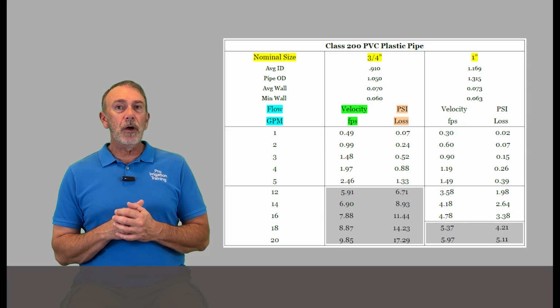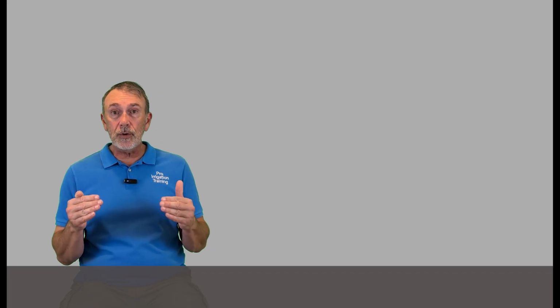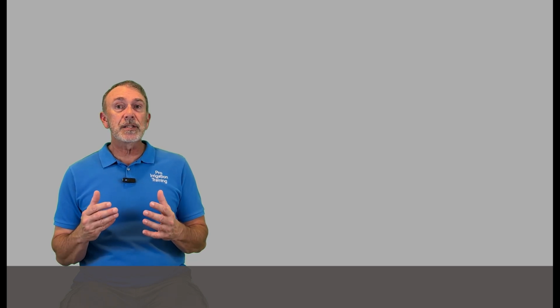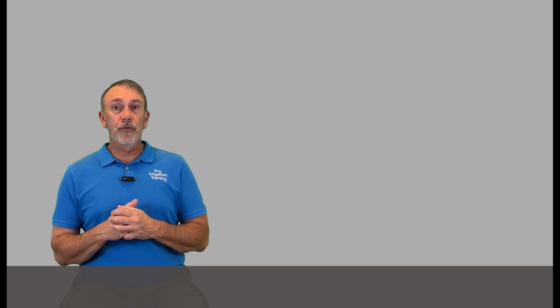And what happens, because velocity is related to friction loss, and of course flow is related to them all, is that we're trying to control our flow numbers so that we can control our velocity. Because if the water moves too fast, there's the concept of friction loss, which is the amount of turbulence that happens in the pipe. And that turbulence scrubs the pressure down off the amount of pressure that we're designing our system for.